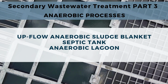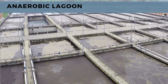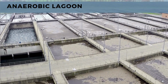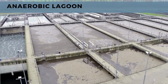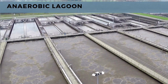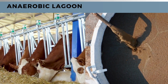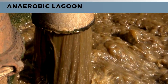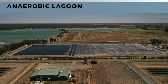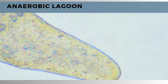Lastly, let us talk about anaerobic lagoon. An anaerobic lagoon is a large, open pond designed for the treatment of wastewater where the breakdown of organic matter occurs in the absence of oxygen. These systems are commonly used in agricultural, industrial, and municipal wastewater management, particularly for livestock manure, food processing waste, and sewage. Anaerobic lagoons operate under anaerobic, oxygen-free conditions and rely on naturally occurring microorganisms to break down waste material.